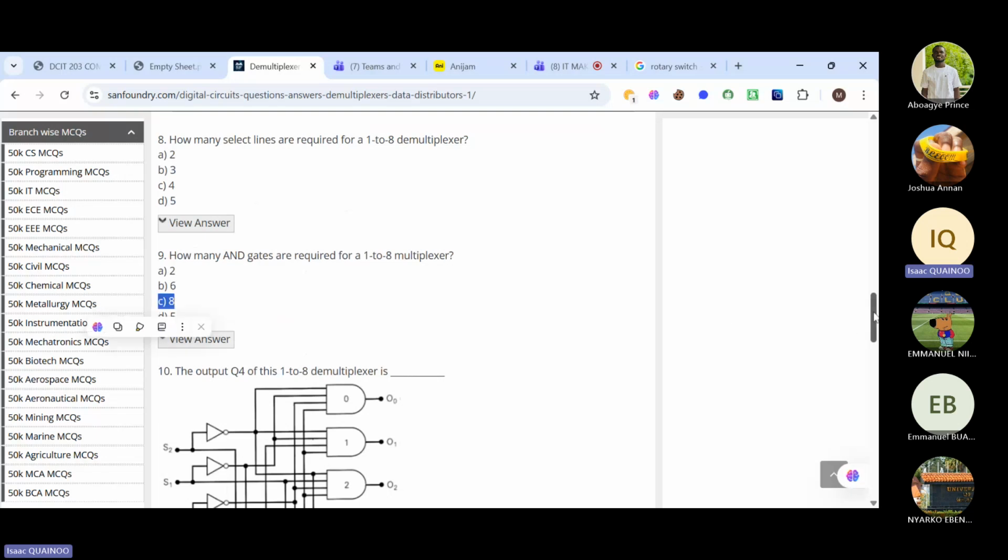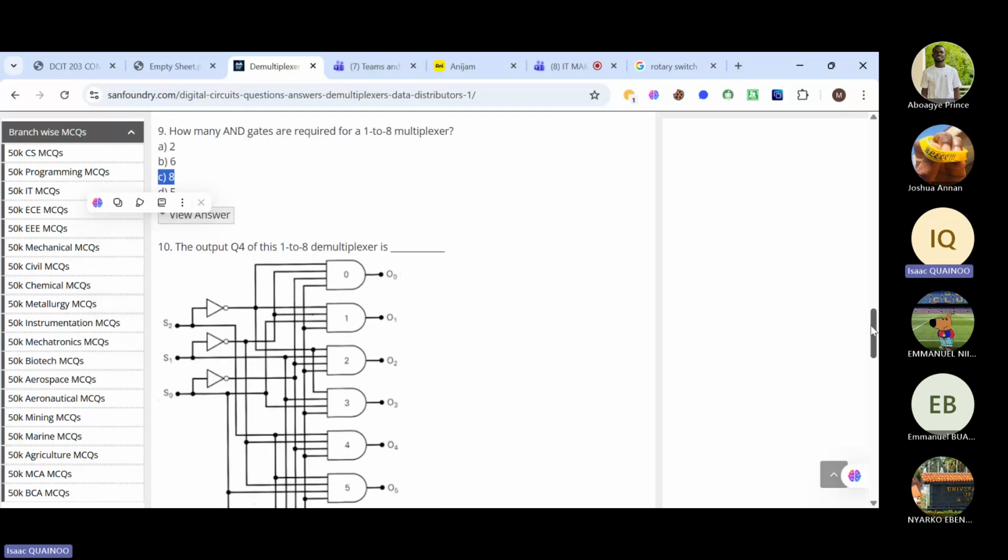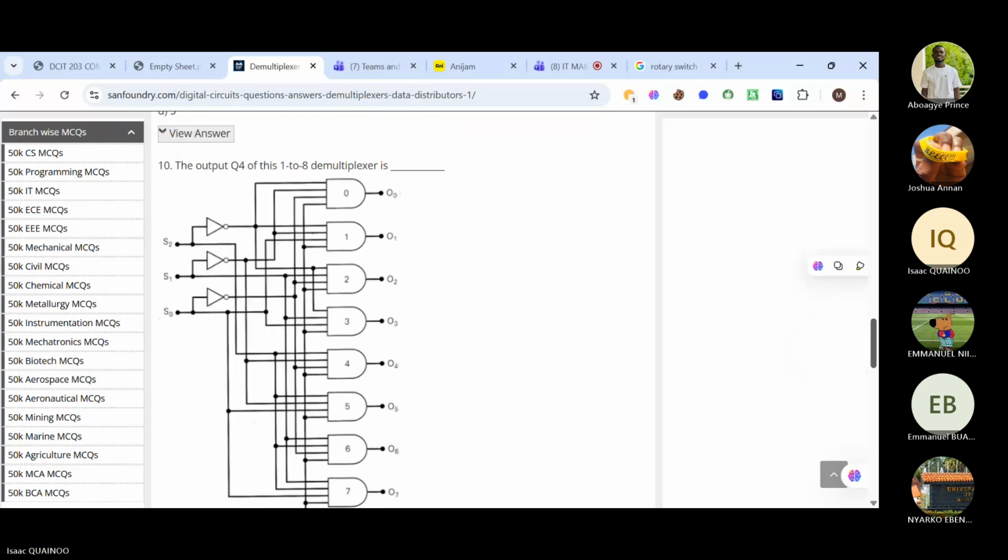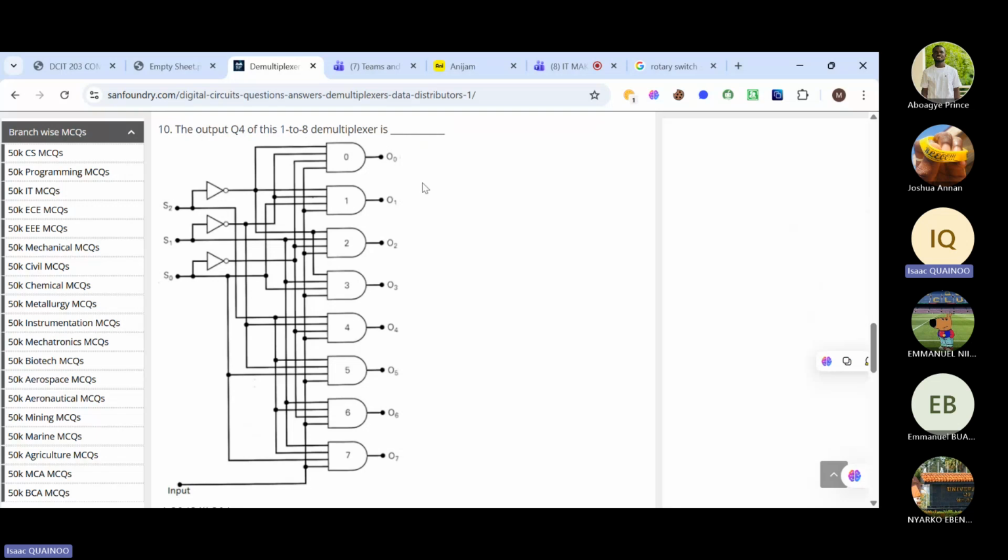And I think if we draw a truth table, each of the expressions for D0, D1 up to D7 will be a sum of products expression. And we know sum of products will always be represented using an AND gate, right? So literally, for the first product term we use an AND gate, second product term an AND gate, and we have 8 different product terms for D0, D1, D2, D3, up to D7. Each is going to be implemented using an AND gate. Please, can someone tell me why we didn't join everything together using an OR gate?